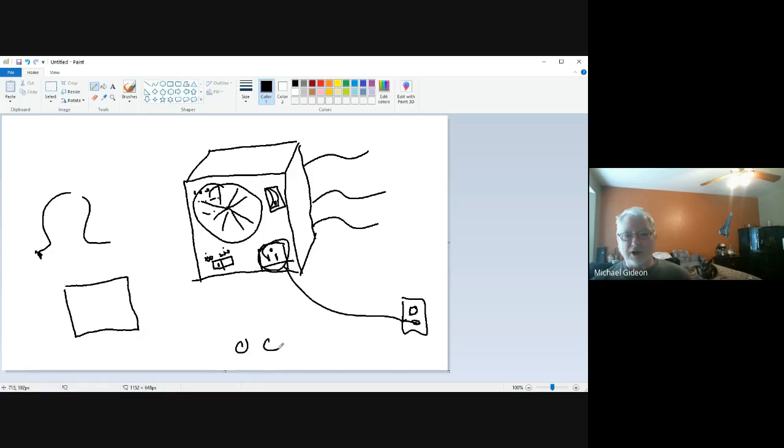You've got your car and a battery inside that car. There's the hood, okay? In here's a battery with a plus and a minus. Your plus goes, it's a big red cable, right? If you ever had to jump a car, it goes down to the starter and the alternator, everything that's all connected together. The ground goes straight to the frame of the car. Your entire car is grounded.